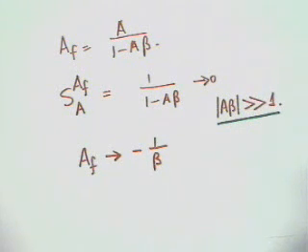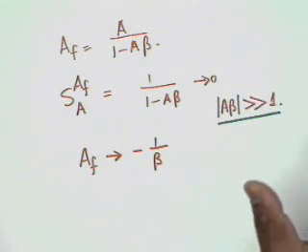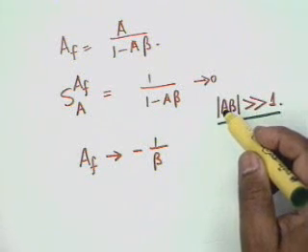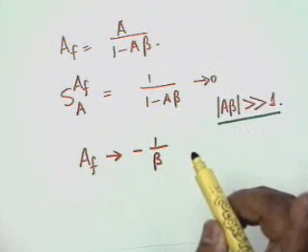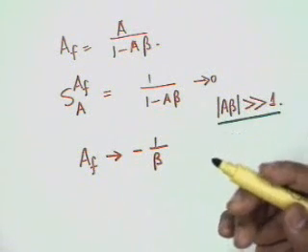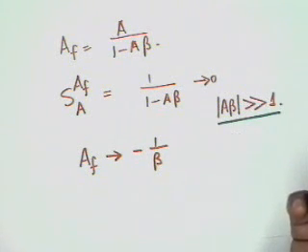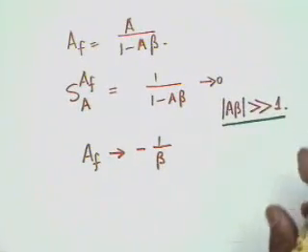Isn't that right? If there is positive feedback, it cannot exceed 1, because as soon as A beta becomes 1, the circuit goes into oscillation or nonsense, as the case may be, and therefore it is not relevant to positive feedback. Alright, this desensitization is not relevant to positive feedback because the circuit no longer performs as an amplifier, it becomes an oscillator.